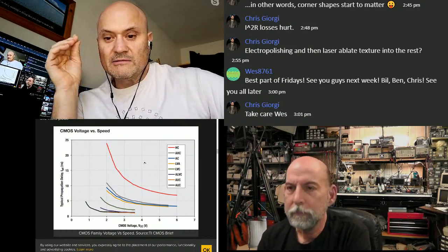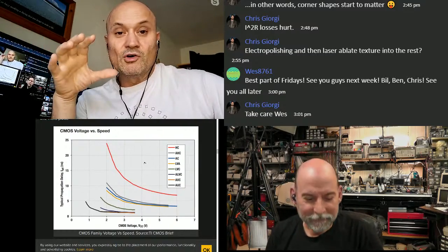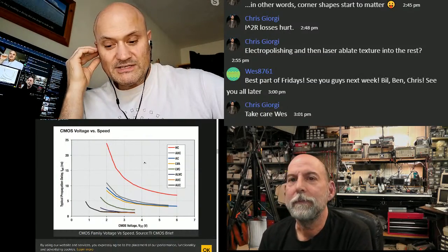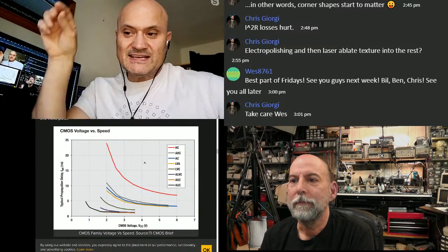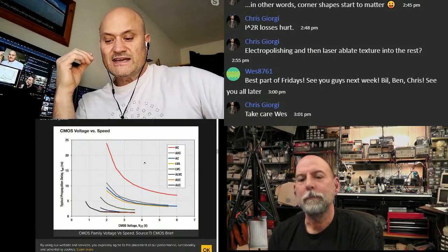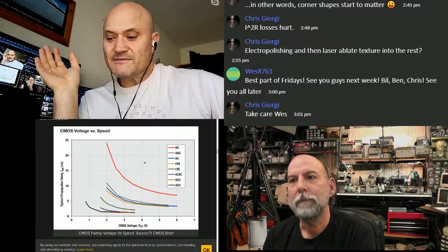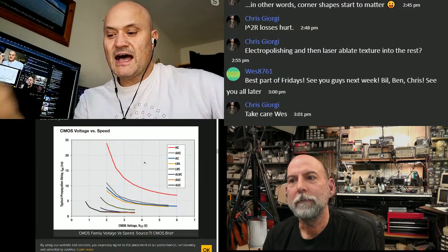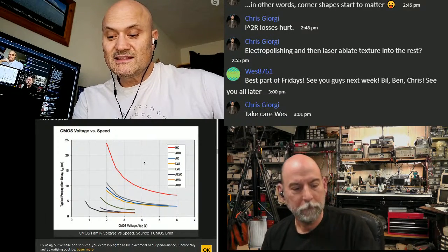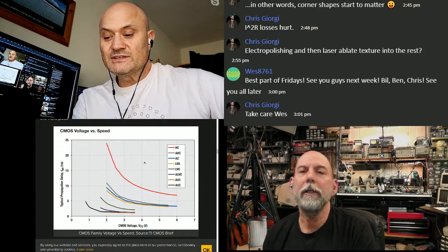You need to be able to measure what they made, not just on the boards that you designed that come out of fabrication, but you should have a test coupon on the edge of the panel that they send you, which has test traces. And there's many different kinds of coupons that you can ask for and that they can build, and they're all standards based. There's a coupon standard that IPC put out, and you can. I didn't know that.